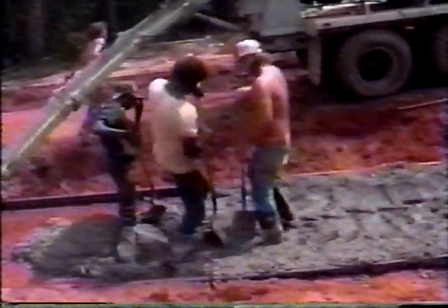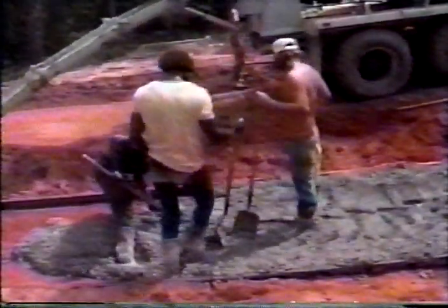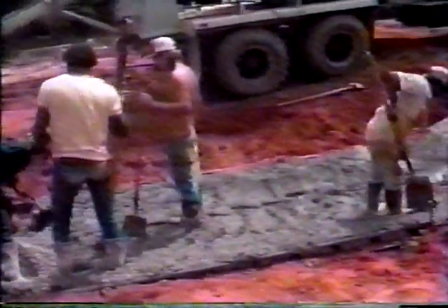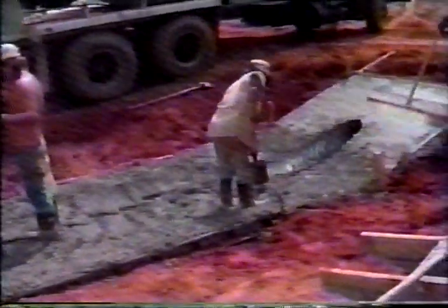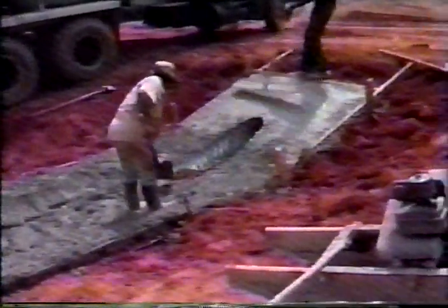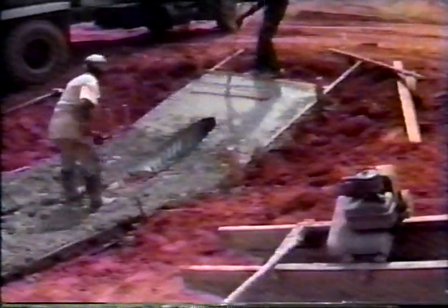Now, temperature. The temperature of fresh concrete affects the rate at which concrete gains strength, the amount of strength the concrete ultimately acquires, and the porosity of the concrete. Checking concrete temperature is simple. It should be done according to ASTM C1064. All that's needed is a standard thermometer, such as an ASTM liquid in glass type, or a metal immersion type.